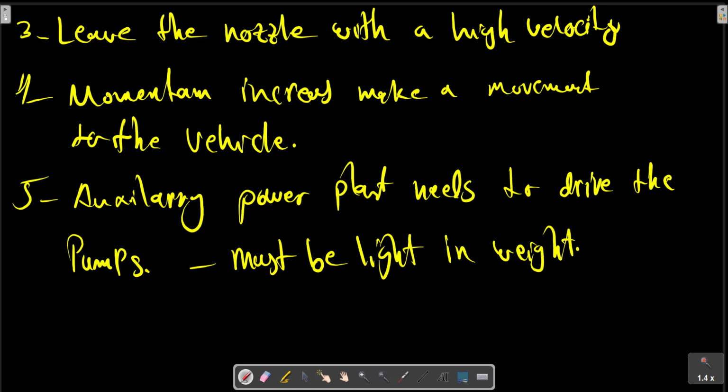The oxidizer and fuel tanks occupy the largest part of the volume of a rocket, and the range and the payload of a rocket are determined largely by the amount of oxidizer and fuel that can be carried. Many different fuels and oxidizers have been considered and tested, and much effort has gone into the development of fuels and oxidizers that will give a higher thrust per unit mass rate of flow of reactants. Liquid oxygen is frequently used as the oxidizer in liquid propellant rockets, and liquid hydrogen is frequently used as the fuel.